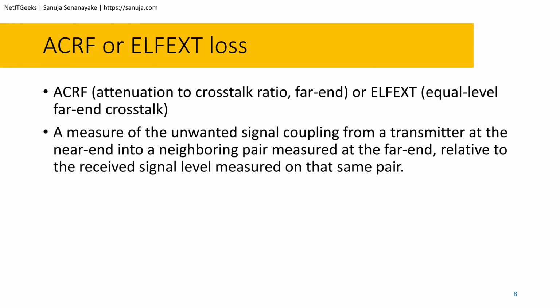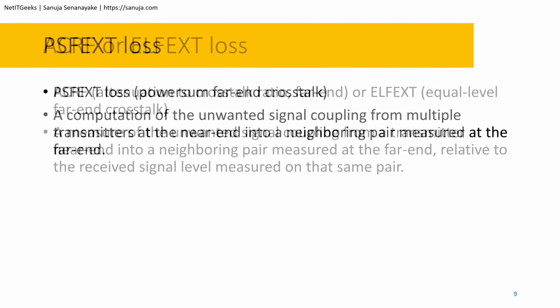So what that means is basically, if category 6 is 200 megahertz, that's the benchmark, that's what we go with, right? That's the standard, that's what the category 6 cable is made for. But the equipment which operates on that category 6 cable may be operating outside of that 200 megahertz rated for that ACR. So keep that in mind. So that's everything for that one.